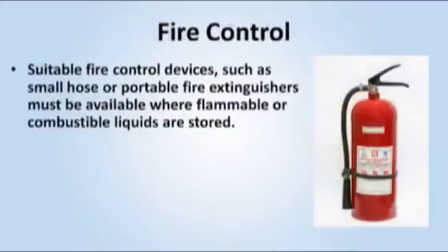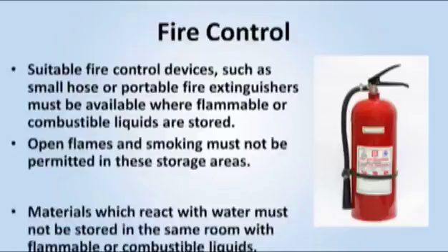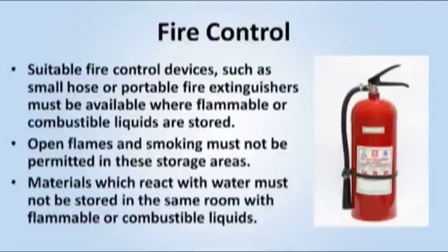Suitable fire control devices, such as small hose or portable fire extinguishers, must be available where flammable or combustible liquids are stored. Open flames and smoking must not be permitted in these storage areas. Materials which react with water must not be stored in the same room with flammable or combustible liquids.